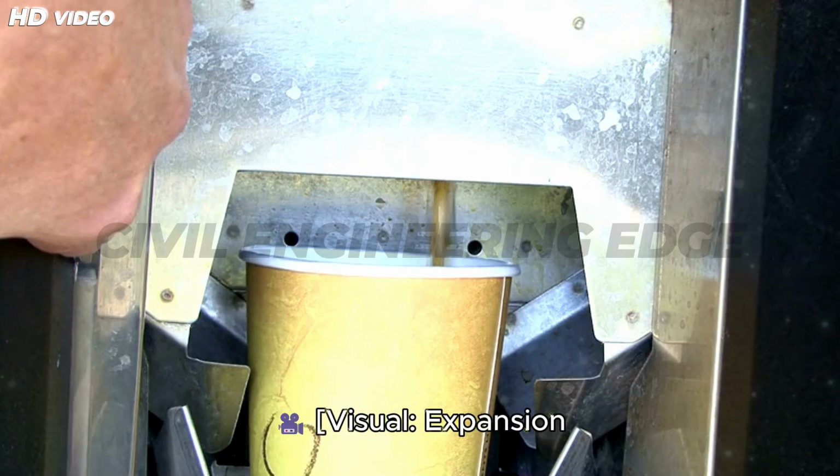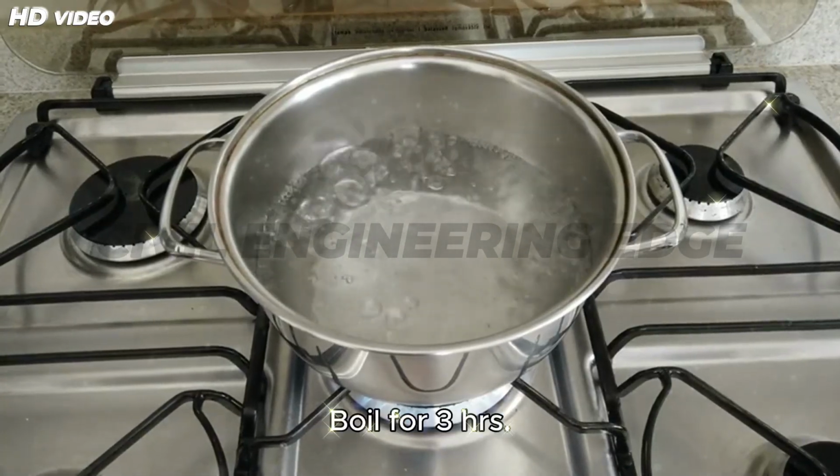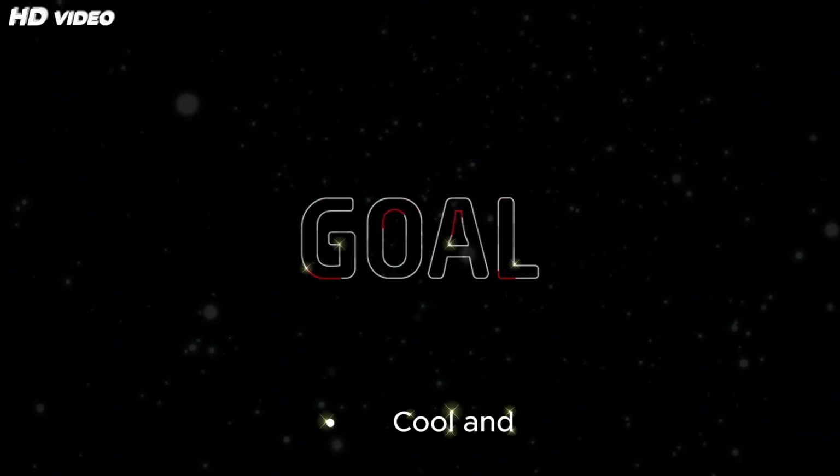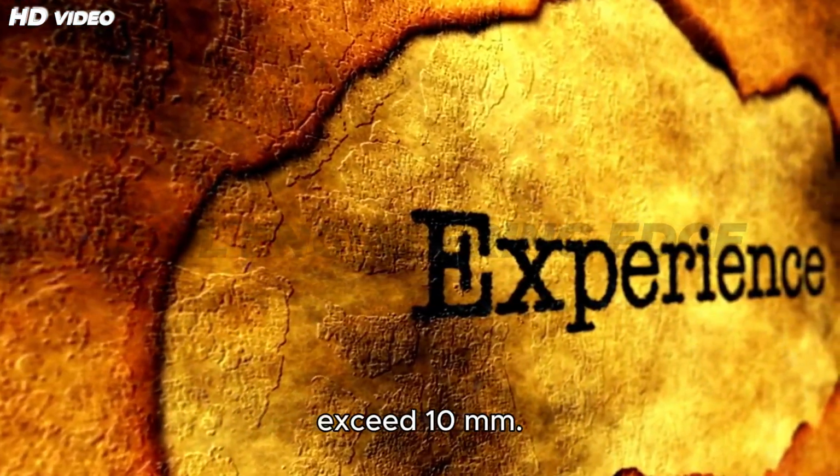Visual: expansion mold with calipers, boiling water tank. Then boil for 3 hours. Cool and measure the final gap. Expansion limit should not exceed 10 millimeters.